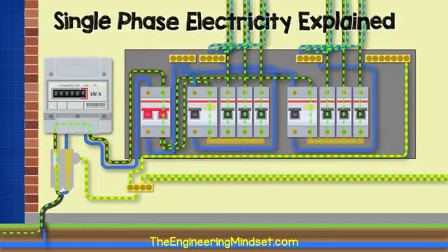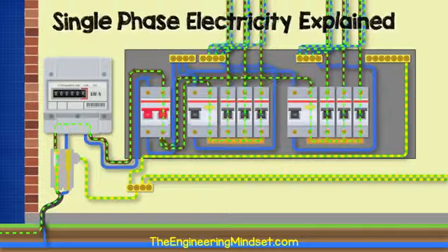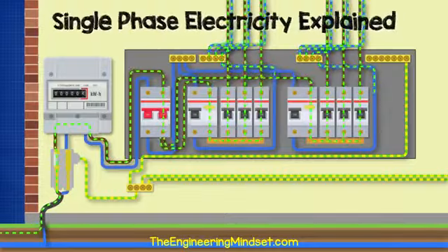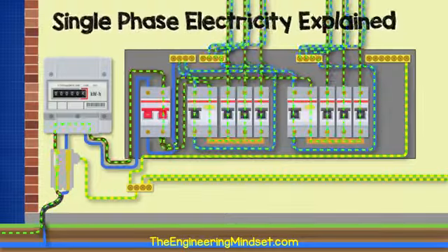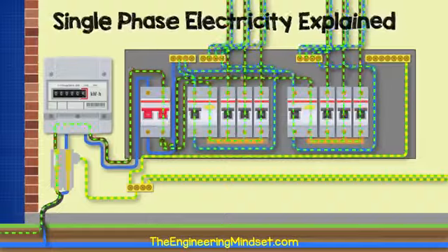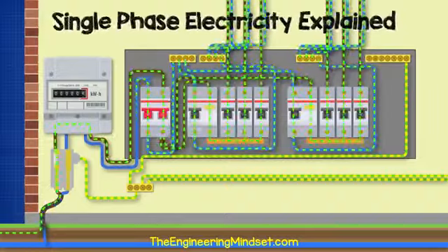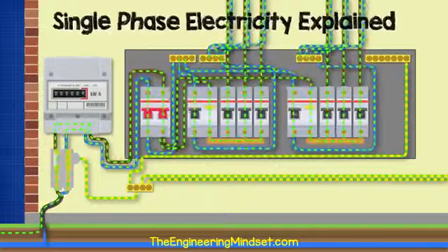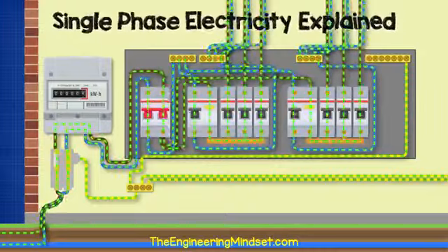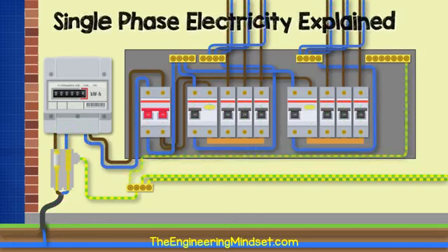The electricity can then come back via the neutral lines and into the neutral blocks. It then flows through the RCD and back into the main block. From there back into the main switch and then the electricity meter. It will then pass through the service head and the fuse and back into the neutral line of the main distribution cables. Now you may have noticed that there's some other cables with green and yellow stripes.